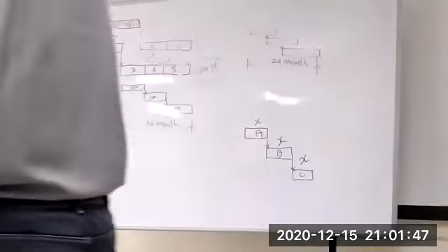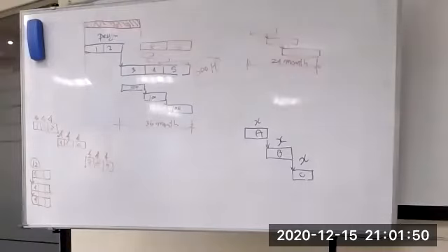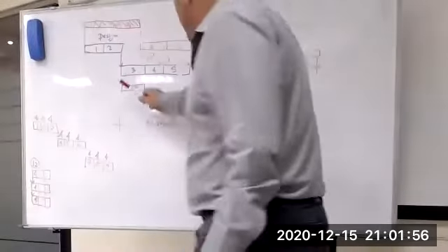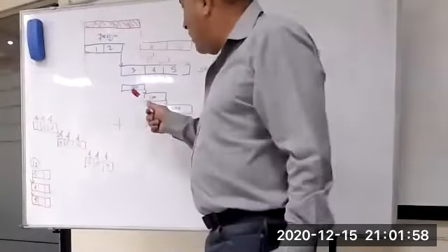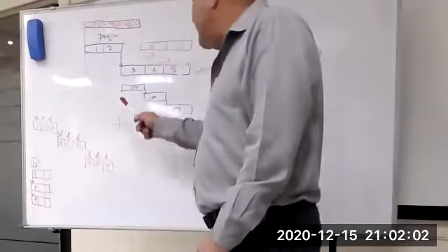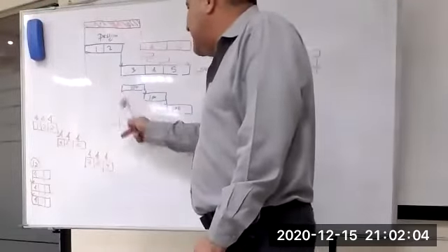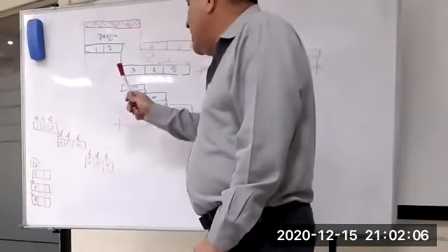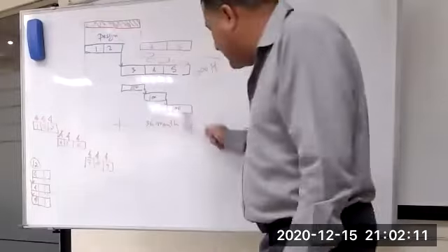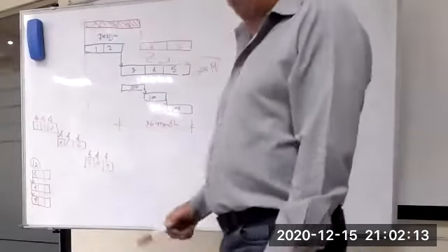It means you have to put all the shuttering activities in milestones. Say you have 300 villas, and you need to get all the shuttering activities as milestones. So the first shuttering activity for the first villa, and the last shuttering activity for the parapet in the last villa.